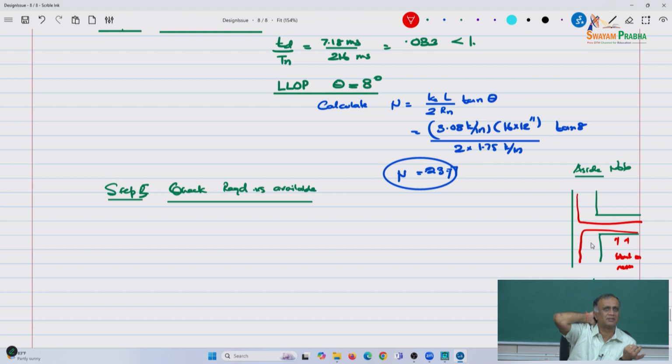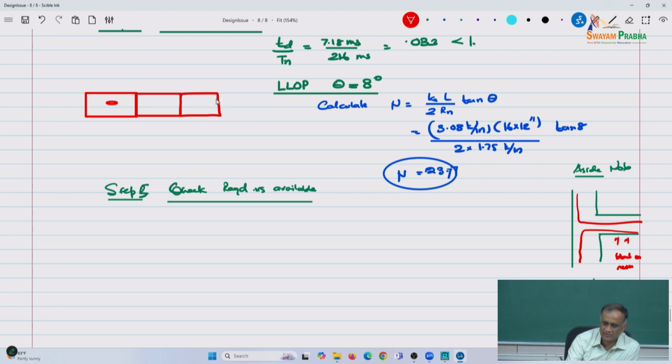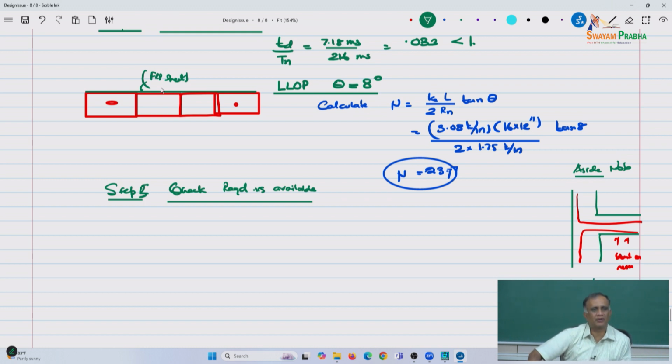Design of connections is everything, even in simple reinforced concrete and seismic design. So in masonry, addressing this, one way to add integrity to it is, let's say I was doing this and I was using these blocks, right? Say every 3 blocks, I might put a sheet at the back. This could be an FRP sheet. I'd recommend an FRP sheet at the back. So this is your reinforcement, this is non-grouted, but this is grouted. That way the whole unit acts as one.